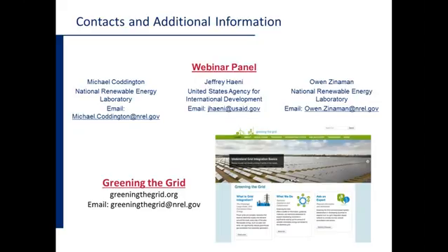But back to Germany, I think that they had a countrywide goal of rolling out PV systems, and it was kind of a situation of damn the torpedoes, full speed ahead. We'll figure out the problems when we get there and try to solve them. And they indeed have seen problems in Germany. And one of the biggest problems is that they generate so much PV power during certain times that they can actually see the frequency in the grid rise higher than the 50 hertz that they try to operate within.